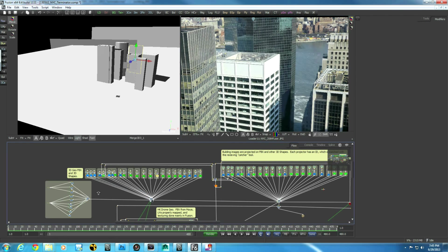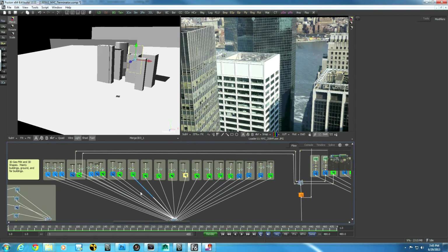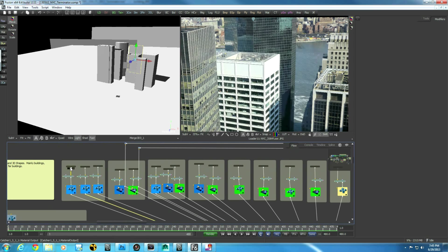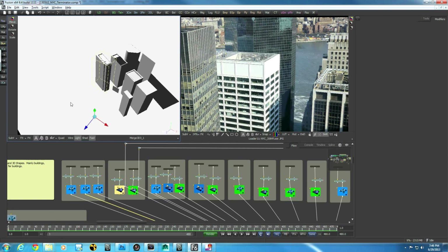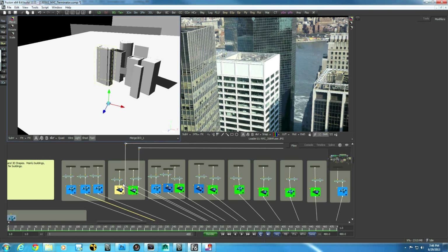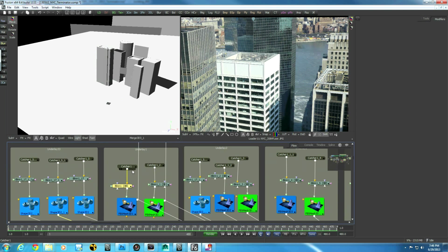There is one other thing that I want to talk about, and that is the way these Sketcher tools are set up. So you have the FBX here, right? So here is the first building. I call it building number 1, and this building number 1 has material applied to that, and in this case it's Blinn. I could have connected Sketcher directly to FBX, but whenever you have texture projection and you are also going to use lights in the scene, in my experience you cannot combine both of them without having a material node to respect the effect of the lights.